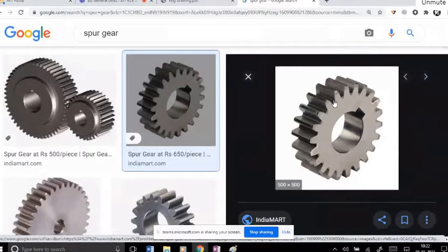That is one of the important applications of involute, because it has certain advantages. It can maintain the pressure angle, so the contact point will always be a line, not a surface, so the energy loss or heat generated will be minimized. These are a few applications. This is the basic introduction about gears and the application of involute, which is the gear. Now let's go to the